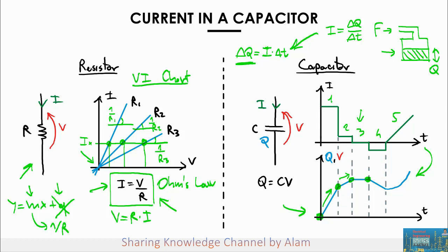And finally, in the fourth period, the current is small, but it's negative now, which means that we are taking the water out of the tank somehow at a constant rate. So that means that the level is decreasing at a constant pace, just as a straight line, and it will settle to a certain new level at the end of the period.